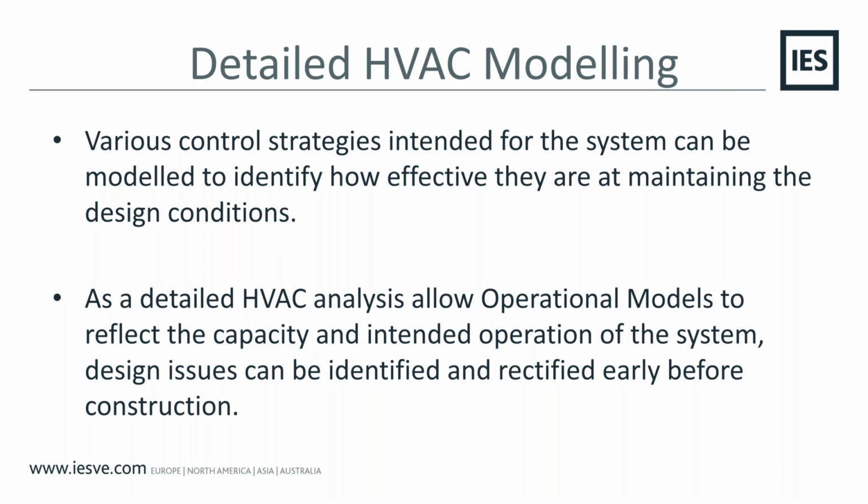However, by doing a comparison using a detailed HVAC model, intricacies such as ensuring the room dew point temperatures don't drop sufficiently low that condensation becomes an issue with the chilled beams, and what impacts we see from running at higher water temperatures in the case of passive chilled beams, can also be interrogated to give us a much more accurate comparison of the potential advantages and disadvantages of the two different systems.